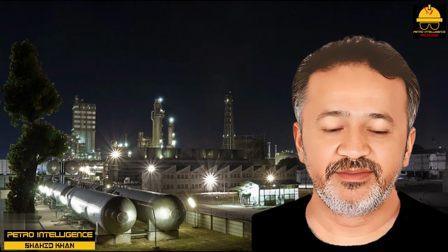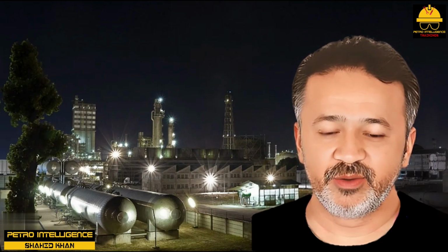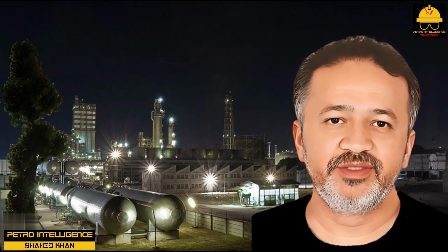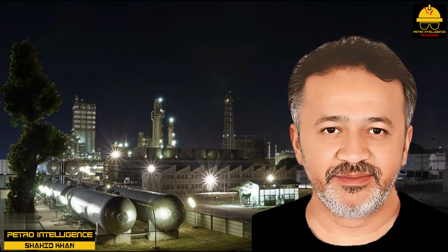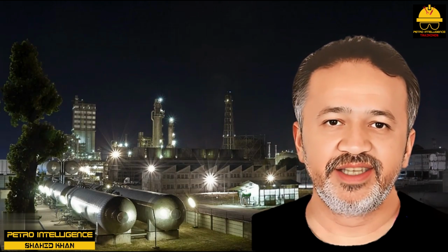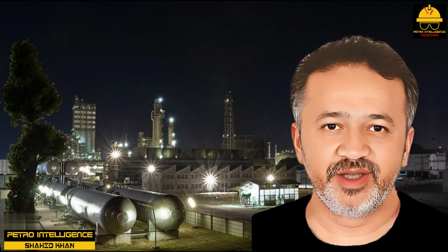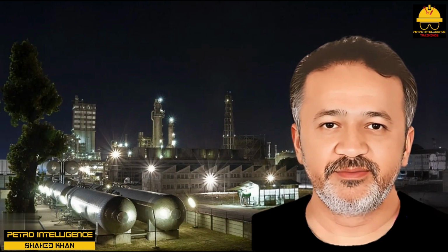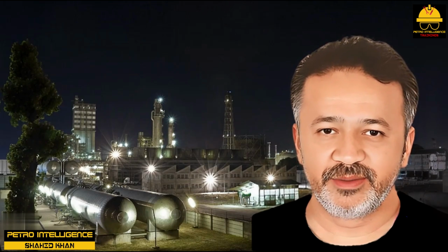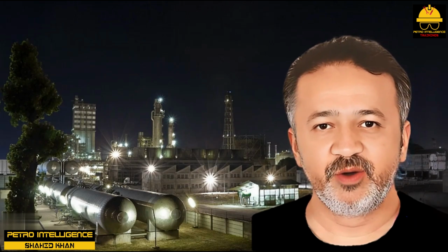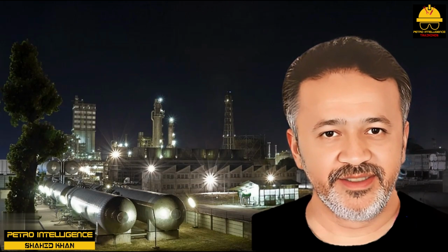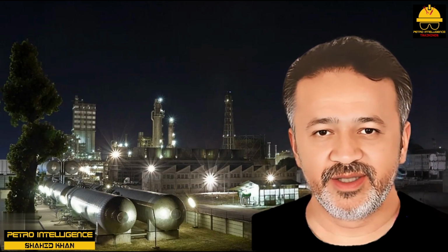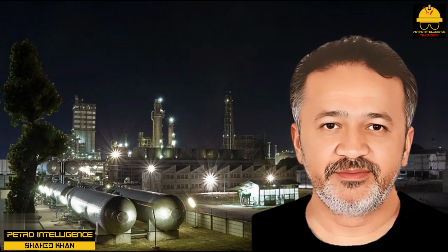Naphtha reforming. This is an endothermic reaction in a hydrogen environment taking place in the vapor phase. The catalyst is the size of grains of rice and contains very costly platinum, which sells for twice the price of gold. The objective is to produce aromatics: benzene, toluene, or xylene. Benzene and xylene are the basic building blocks of the chemical industry.